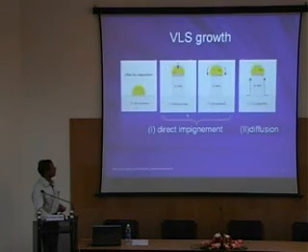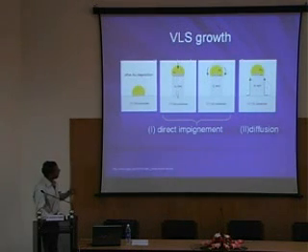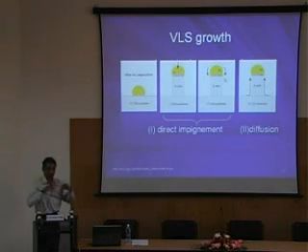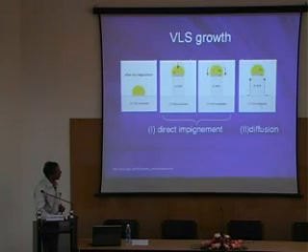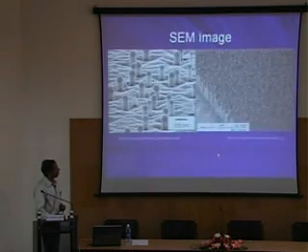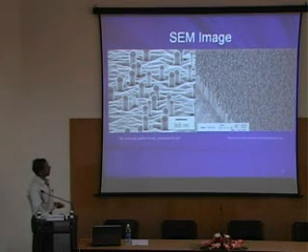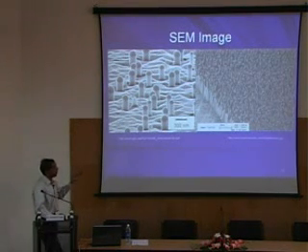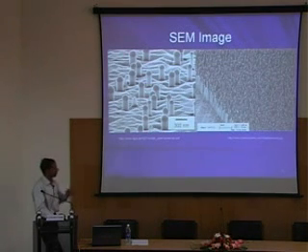Here I have shown a better picture of how silicon nanowire growth takes place in VLS. You have the metal droplet here, and the silicon atoms from the vapor come and reach the interface, and the silicon nanowire grows here. As more silicon atoms come from the vapor, either from the sides or from the top, the nanowire keeps growing. You can grow several microns of length, and millions of these nanowires in a given area on top of the silicon wafer.